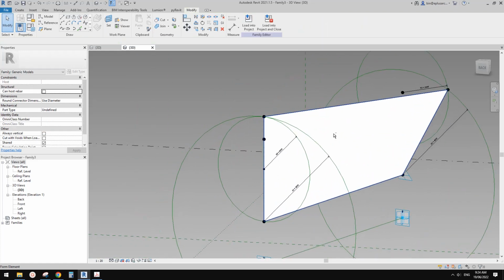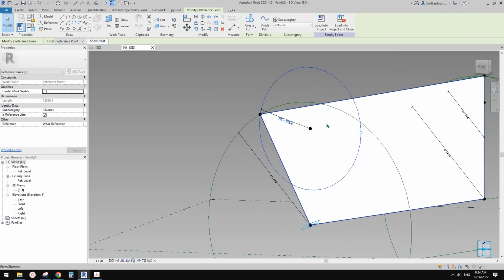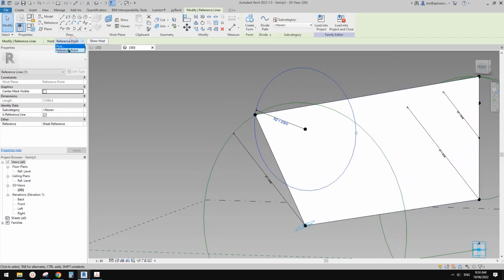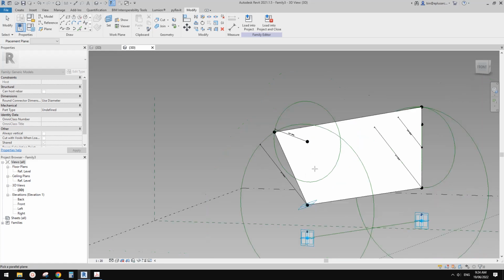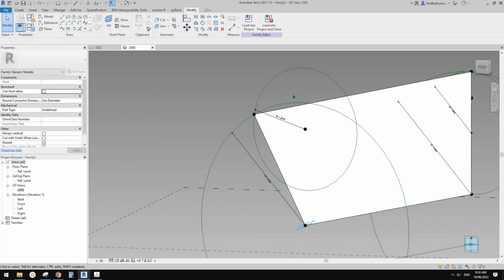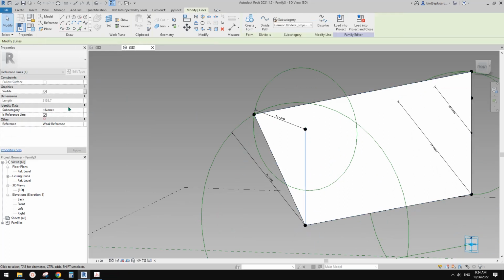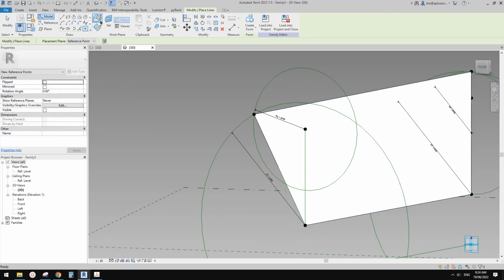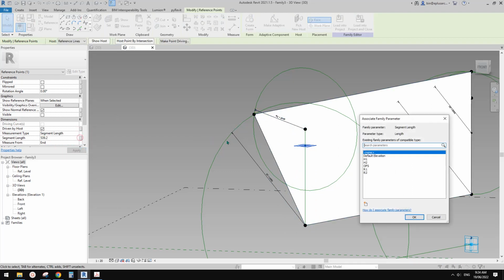Okay, the same, select this. So we don't need to redo it. We can first change the work plane of this circle from this point to, we don't have this point yet, so that's fine. So select these two, create a spline, make a reference line, draw a point, use draw on face, select this point, change the direction so it starts from this point, change to section length, and apply this